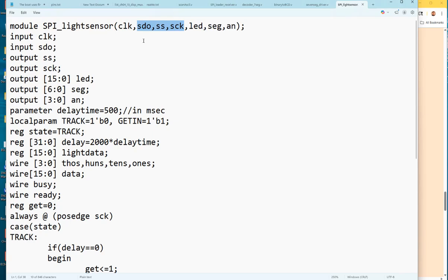Would we just make a wire to them? No, these have to show up in the constraint file actually. Whatever you're putting here has to be identified in the constraint file. But you don't have them, right? Then just change the name of the ports in the constraint file. But what are the ports you want to change?